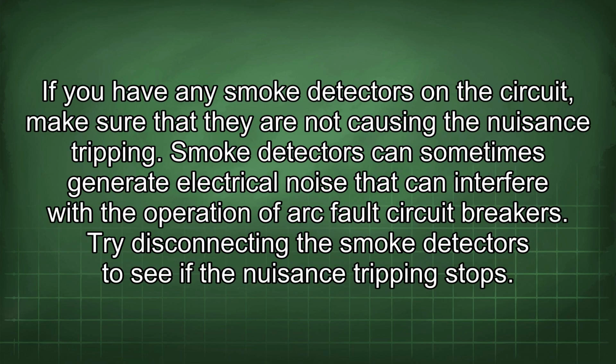If you have any smoke detectors in the circuit, make sure that they are not causing the nuisance tripping. Smoke detectors can sometimes generate electrical noise that can interfere with the operation of arc fault circuit breakers. Try disconnecting the smoke detectors to see if the nuisance tripping stops.